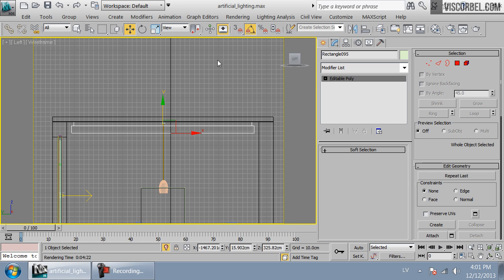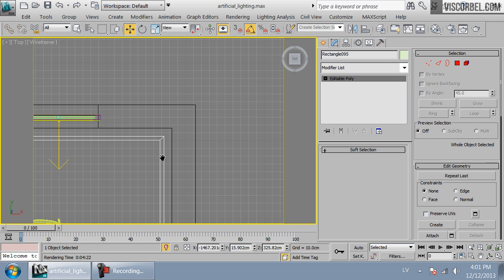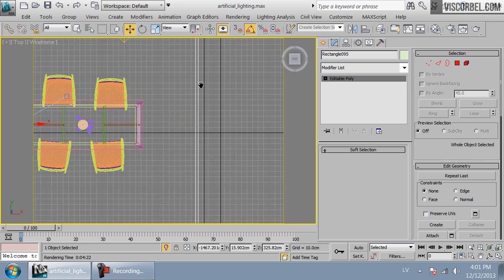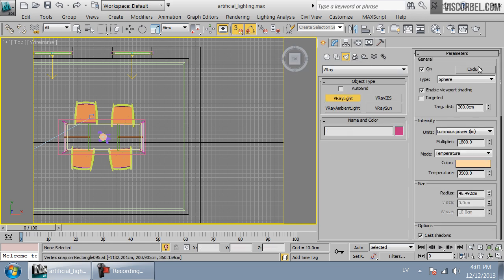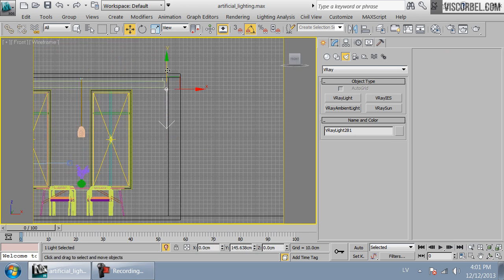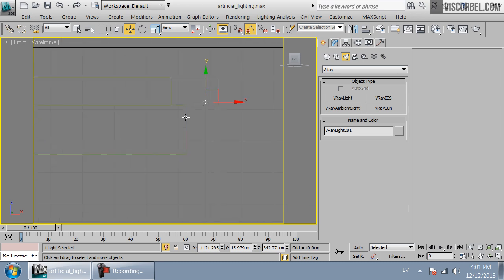And many people that have not seen these lights in real life or do not know how they are constructed usually use a technique like this, where they create a light, point it directly downwards. Okay, so plain light, point it downwards and expect it to look good. That's really not how it works. You do not put the lights in this direction, since if you can see them in render, it looks weird. They are too bright, or they are too aliased, or the light distribution looks weird.